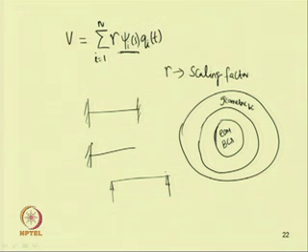But for simpler geometric conditions like simply supported, clamped-free or cantilever, or fixed, as the eigenfunctions are easily available, one can take those eigenfunctions easily for the analysis, and also one can use the orthogonality property of these eigenfunctions to find the governing temporal equation of motion of the system.